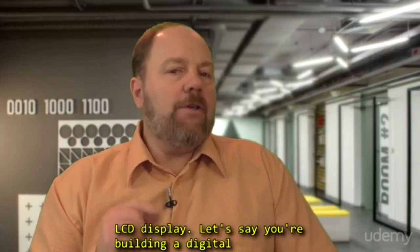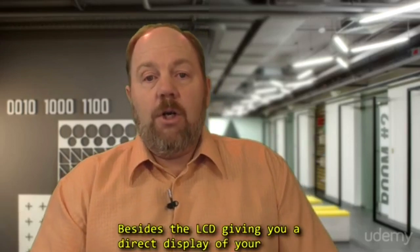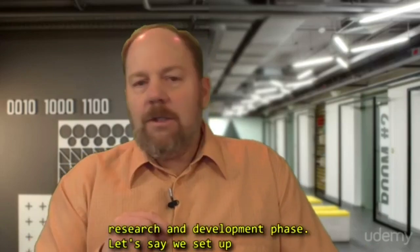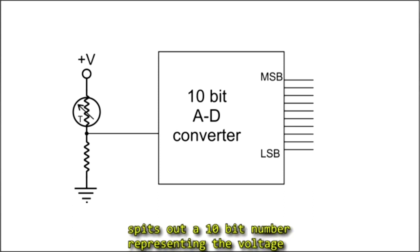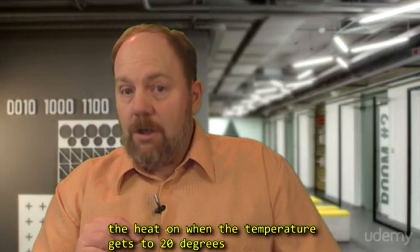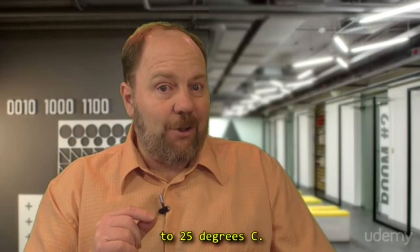Let's say you're building a digital thermostat to control the temperature in a room. Now, besides the LCD giving you a direct display of your settings, etc., it can be invaluable in your research and development phase. Let's say we set up a thermistor with a resistor as a voltage divider across the power supply, and the analog to digital converter spits out a 10-bit number representing the voltage coming out of that voltage divider. Now, I want to turn the heat on when the temperature gets to 20 degrees Celsius, and turn the heat off when the temperature gets to 25 degrees Celsius.